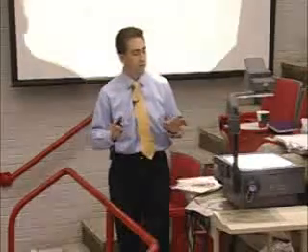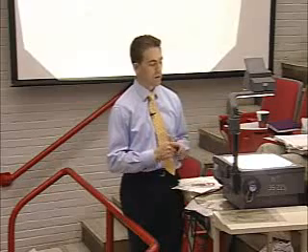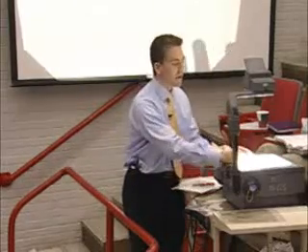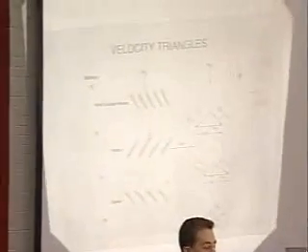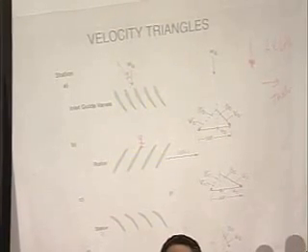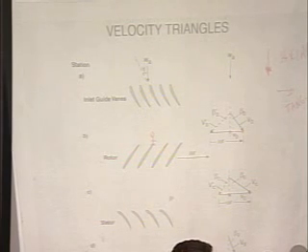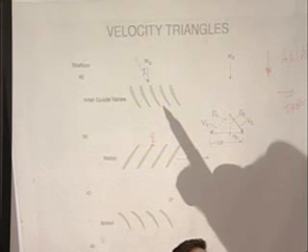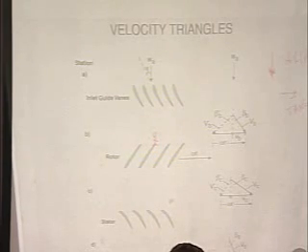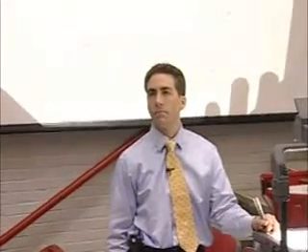Okay, now I want you to do the same things that I do on your handouts. We're going to follow these rules. The first thing that we said to do is check the incoming angle of attack of the flow. From the perspective of an airfoil, this would be the angle of attack on that airfoil. You have to put yourself in the frame of reference of sitting on an airplane's wing here. The higher the alpha, the higher the angle of attack. But that's reasonable. You'd expect to have a positive angle of attack coming into these blades. If it were negative, you might worry a little bit that something was wrong.